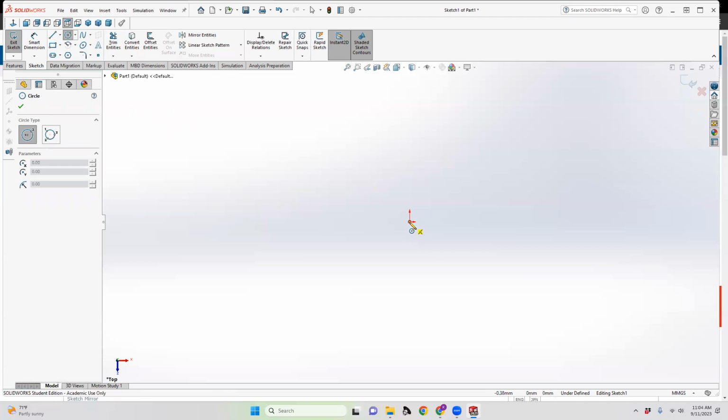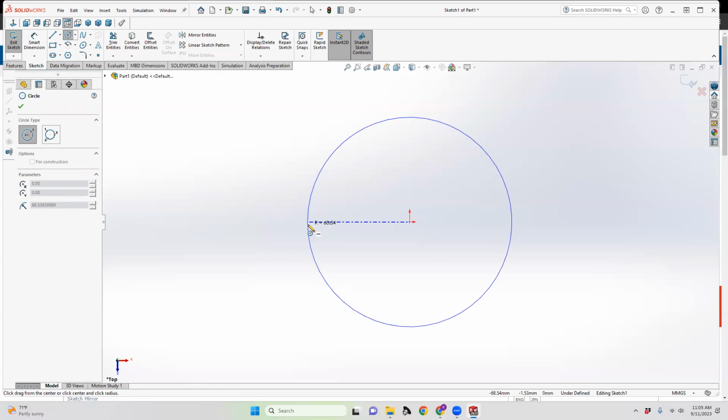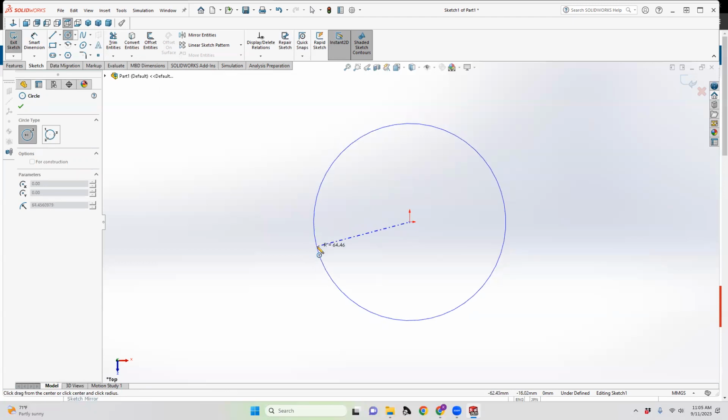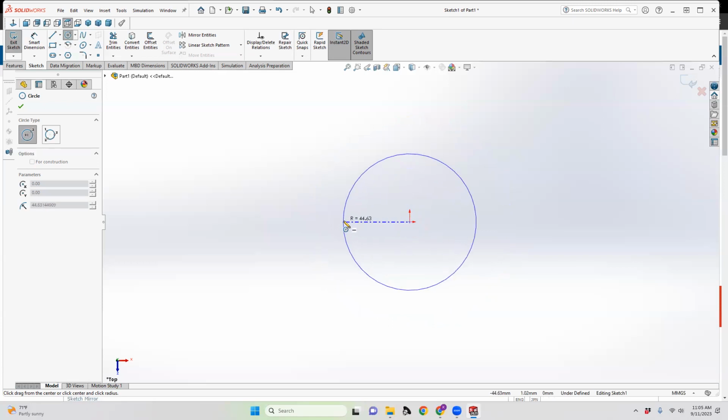So to grab a reference point, anytime you see these, you guys won't be able to see it really on the screen very well for whatever device you're on right now, but there'll be a little yellow symbol that has a couple points intersecting. There's a couple things about the cursor that'll tell you information about relativity and reference points. So it's important to understand some of what those are. So right now, this one is just telling me my point is actually at an intersection. So my point is actually at what's called the origin, which is 0, 0, 0. Now, if I take this at an angle, that white line goes away. That white line shows up again, meaning I have a parallel reference point.